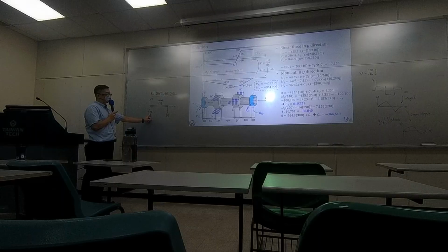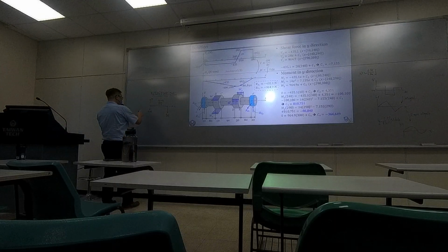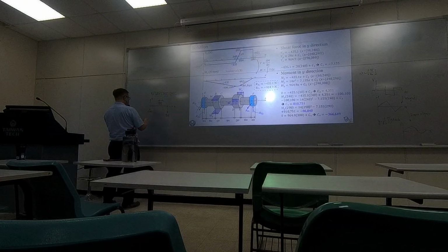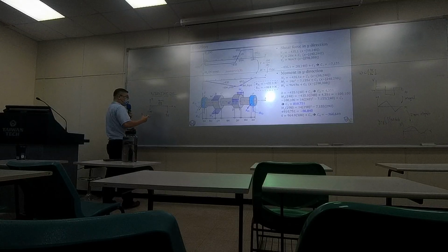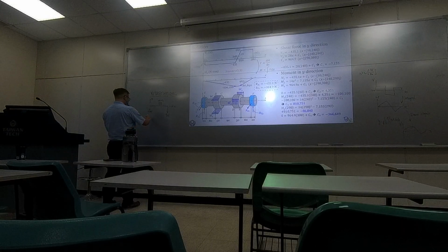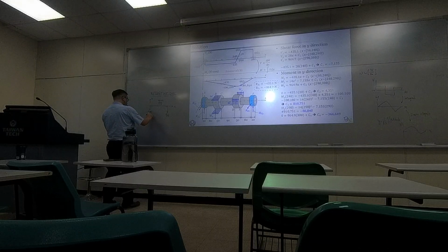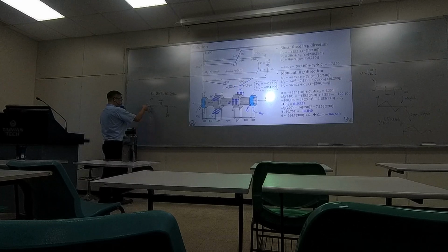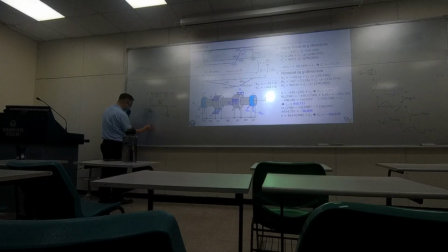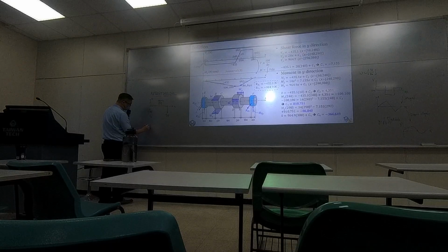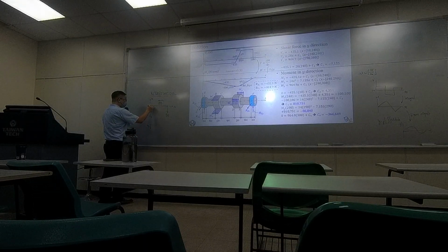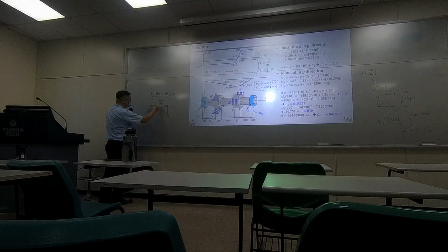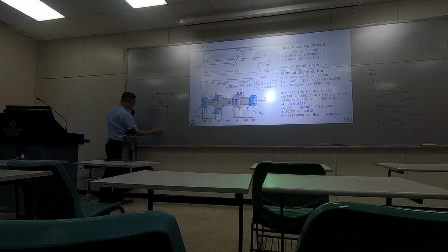You can start from the left. When you take the walk, when you see any forces along the y direction, that instantaneously changes the shear force at that particular point. So this is V along the y direction. So right here, you are already being pushed down, so there is a shear of 435. And if you take more walk to the right, there are no more other forces, so this shear force remains until you walk up to here.